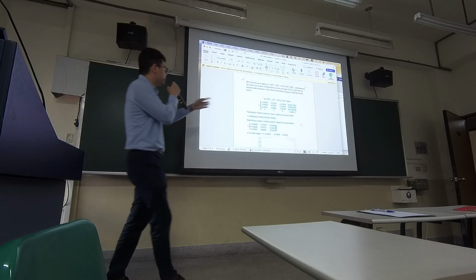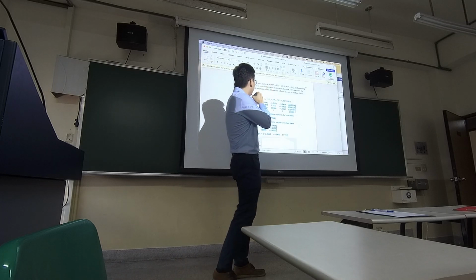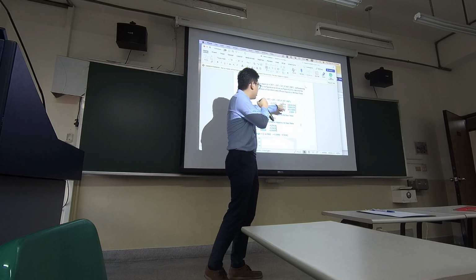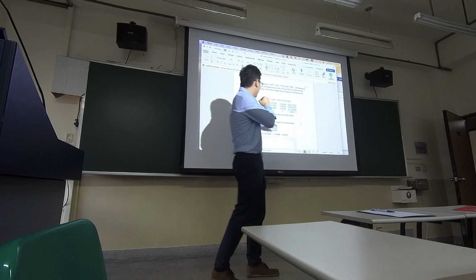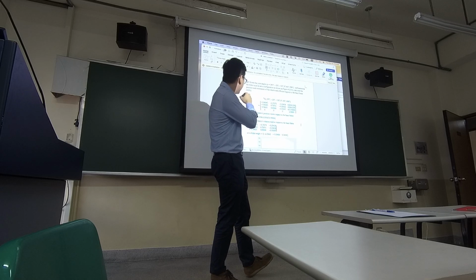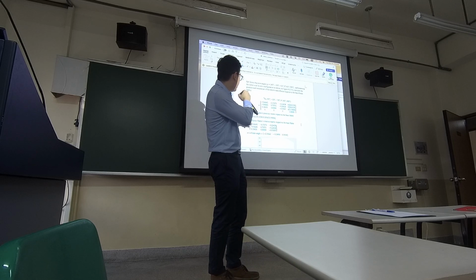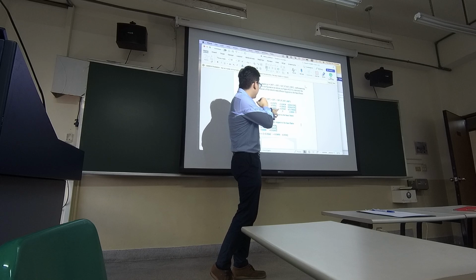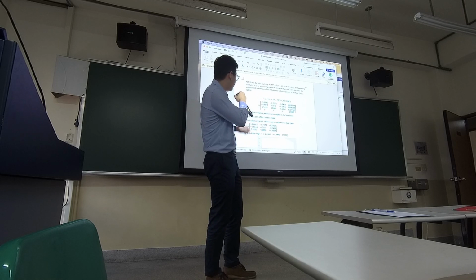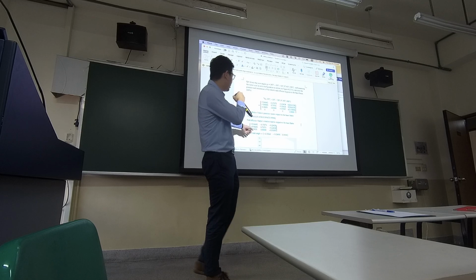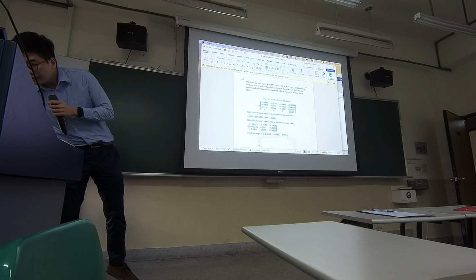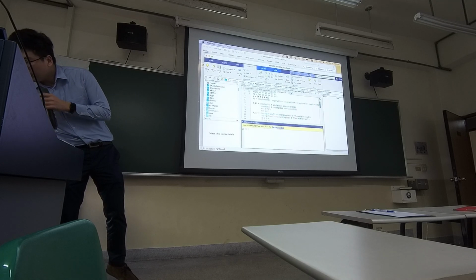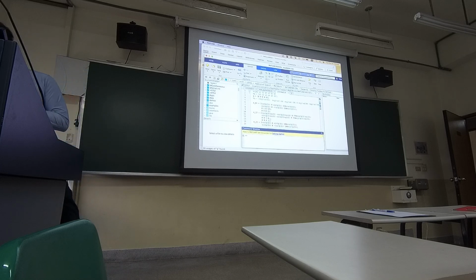And the last question is, this is the input angle, and through the input angle, you get this transformation matrix, and you can express the last column as the position vector, and this 3 times 3 matrix is the rotation matrix, or you can express it in Euler angles. And I'll quickly show you the MATLAB function.